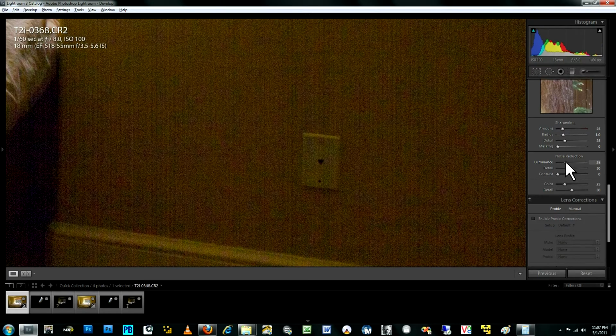And so I think I'll start at like 30, which is even higher than what I did for the 5100 image. And you can see the banding has softened a little bit, but it's still very obvious. And even worse, that blotchiness has actually become more apparent as I've increased the luminance, because I've reduced the detail, or the apparent detail, of that hatching pattern, which isn't really true detail, but just this false noise detail that's been introduced. So that makes the blotchiness of the colors even more apparent.